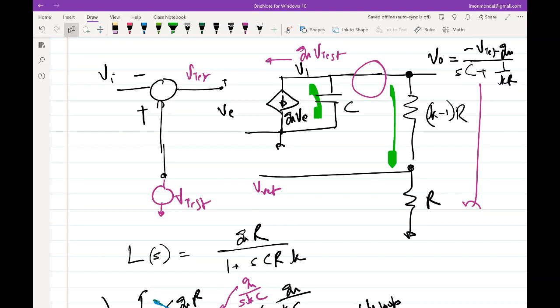Okay. Sir, beyond the pole, the frequency is so high that the capacitive current is so large compared to the current that is passing through this. Right, exactly. It's the low impedance path through the capacitor, so current prefers capacitance. So current path prefers like an ideal case. Correct. Exactly. Okay. Any questions?